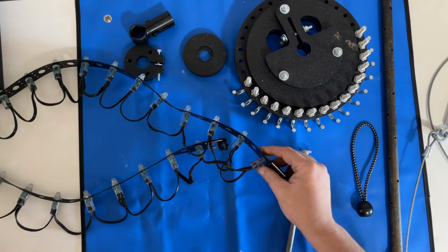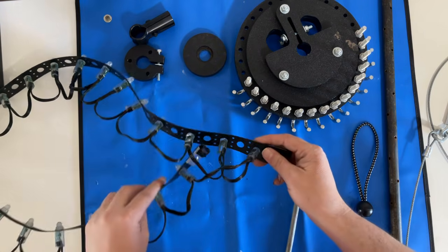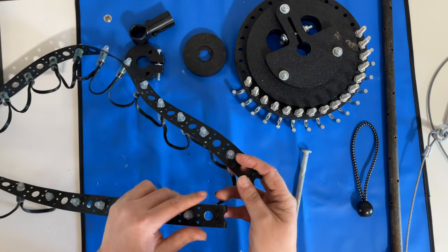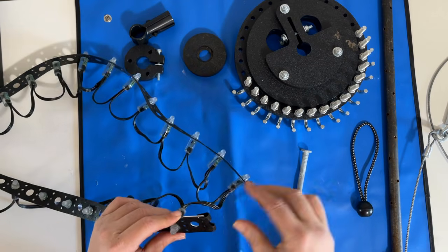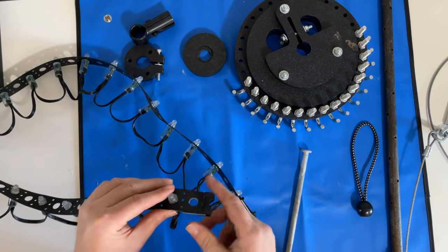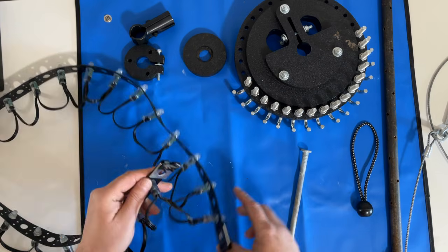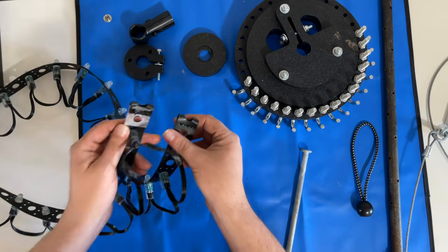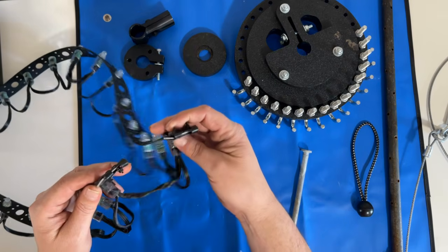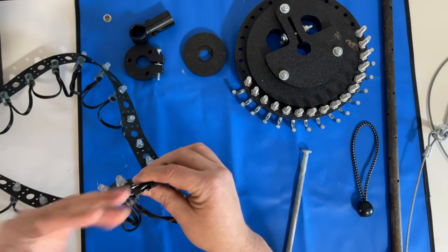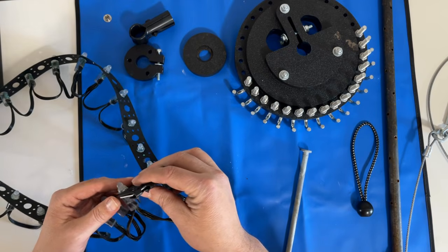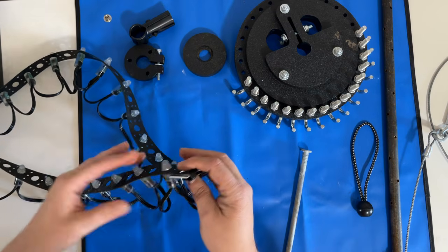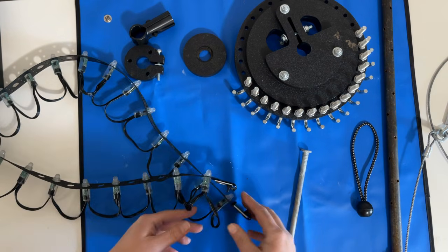And then the top, when you come up, because you got to do strings of 100 lights, when you come up one side, you're just going to start coming down the other side and count off your extra pixel spaces. And then I made it the same way down. When I put them all together too, I marked one of them as silver. So I knew that was the one that went in on the left side, and this one went in on the right side, because data always flows left to right when you do your pixels. So that keeps your chains and your strings in the right spot and in the right direction when you attach them. Something to keep in mind when you're doing that.